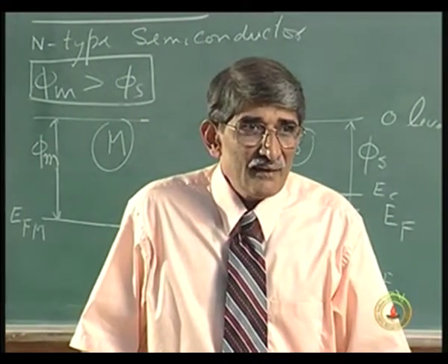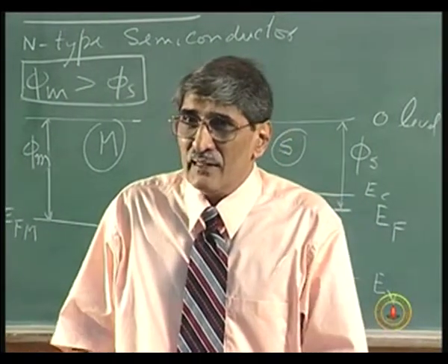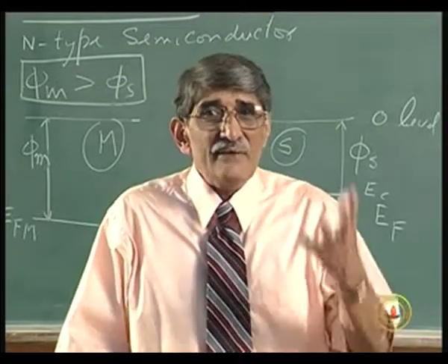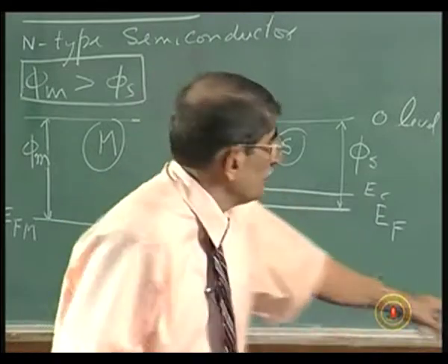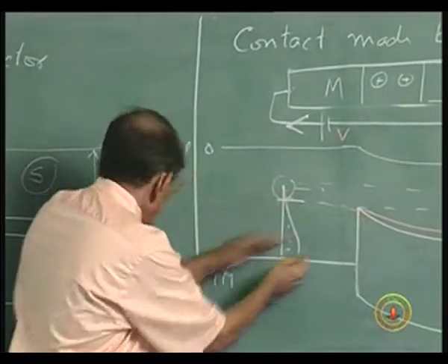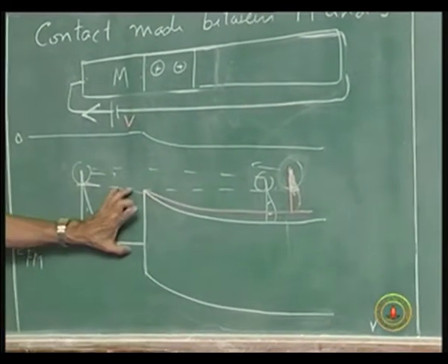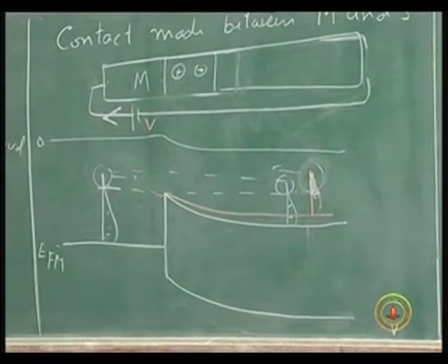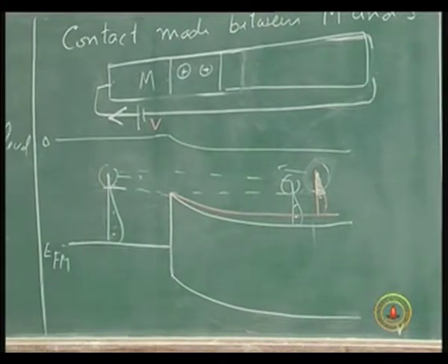That is what I want to say, because it is stretching it beyond certain point and telling you that phi m less than phi s becomes ohmic. It did not become less than phi s. Still, if this barrier keeps on reducing, that is, if this difference is reduced, phi b n, okay, that becomes smaller and smaller. So, it becomes leaky. That is why I just deliberately brought this out.